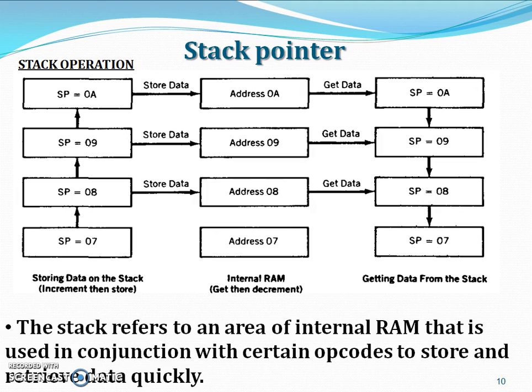By default, the stack pointer address is 07H of the RAM. When we are storing data, it increments and stores by the PUSH and POP instructions. Later on we will discuss how this works, incrementing or decrementing with PUSH and POP, and how to restore the data and copy the data onto the RAM, right? Right now we are pausing here.